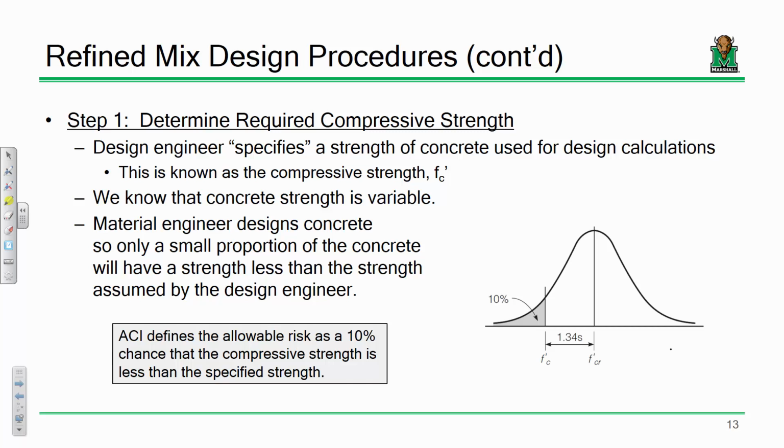Now, it's going to have some load, make up some number. Let's say it's 10,000 pounds until it fails. So 10,000 pounds is the load. Well, it's a cube that has an area 2 by 2, so 4 square inches. If I take 10,000 pounds and divide it by 4, what is that? 2,500. And what are the units? PSI. I propose that for that batch of concrete, its compressive strength is 2,500 PSI, the amount of pressure, the amount of stress that it would take to fail that given element.